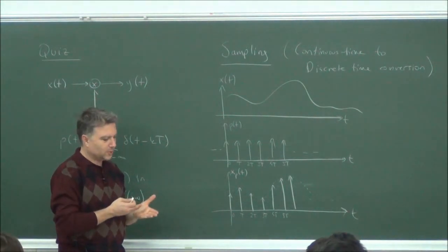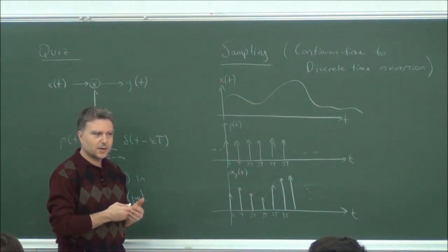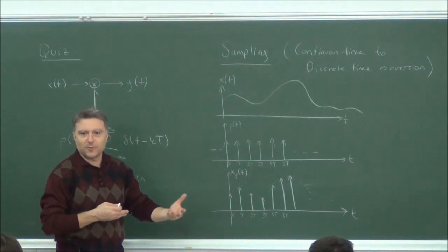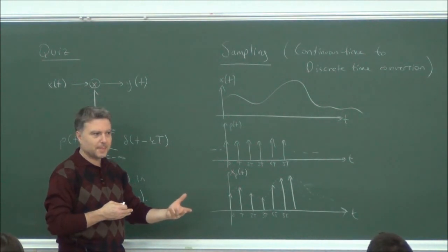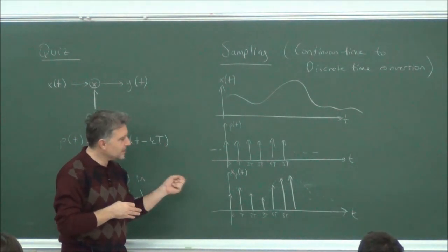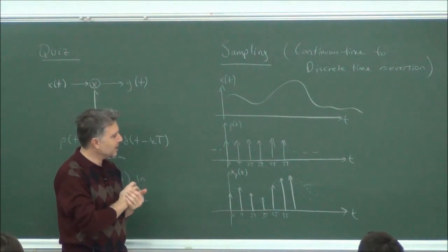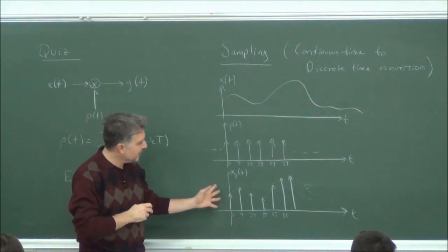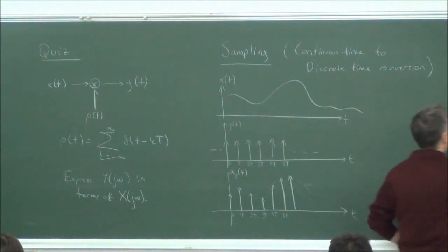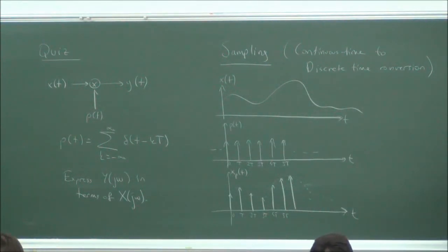Of course, we don't have an impulse train generator inside the analog to digital converter, ADC. We don't do it like this, but this is mathematically the closest thing that we can express. The last step from here to the discrete time version is another hypothetical conversion of the horizontal axis to n instead of t, and expressing this thing as x of n, xd, let's call it. And this xd of n will have the same shape as xp of t.